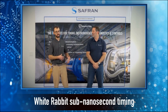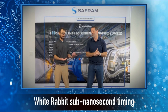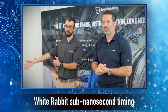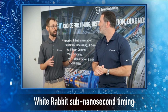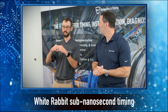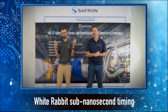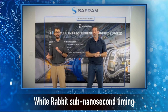We won't get into too much of it today, but NTP and PTP are usually in microsecond level accuracies. White Rabbit allows us to go picosecond over distances and then convert to PTP at the very end, which improves the accuracy to the consumers. One of the harder requirements, I won't call it a downside, with White Rabbit is the need for fiber optic networking connections dedicated generally to White Rabbit timing from point to point. We have a team of experts here that can help design that out and talk through how all of that goes.